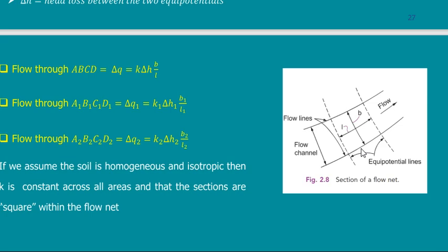If you manage to draw a drawing where most of your squares, of course they are not squares, but where most of your 4-sided figures, you can put a circle inside them, then your drawing is very accurate. If all your drawings include ellipses and something like this, it means that you are getting wrong numbers.